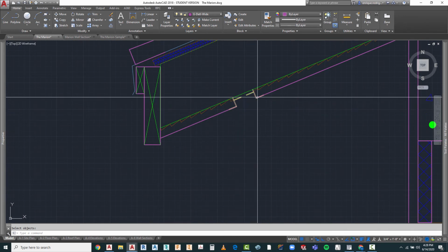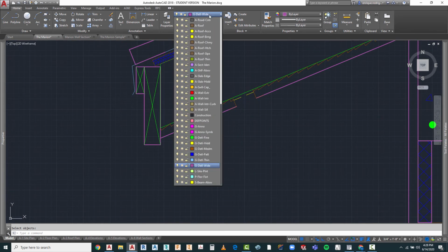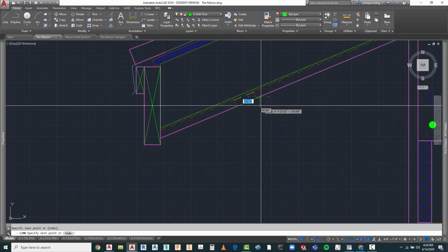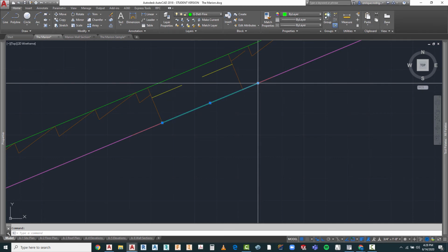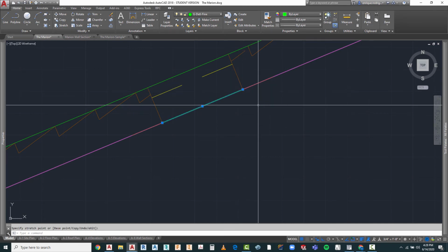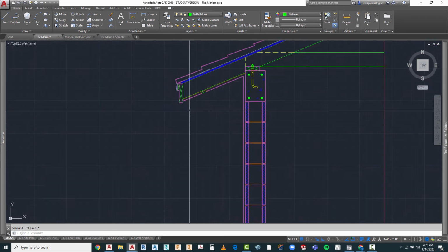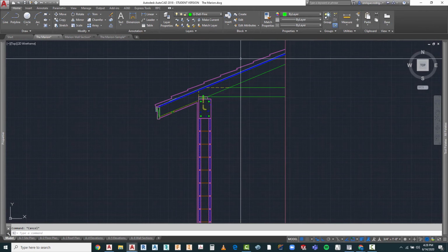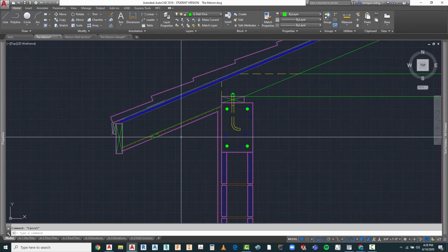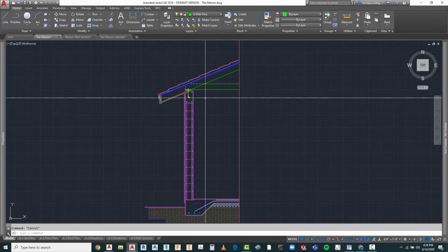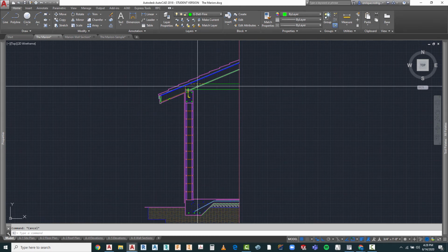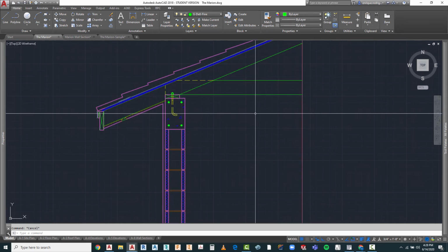You actually do have a very thin line going out there, so I'm going to use the thinnest that we've got, G-detail fine, or you can even use the pattern, which is even thinner. I'm going to grab it by its grip there and put it right to there. All right, so there's our vent. You are required a certain number of square inches per square foot of attic space that you have in your house. You also have other requirements: if you have over 3,000 square feet, you need to separate sections of that roof. All right, that's looking pretty good.